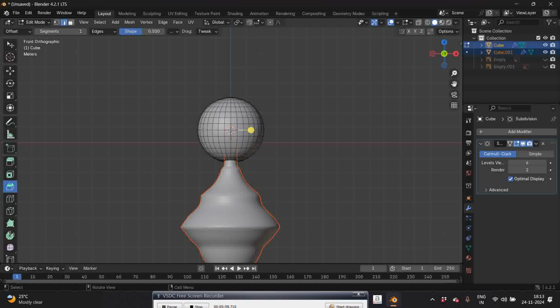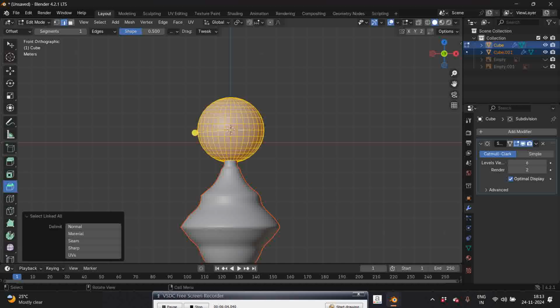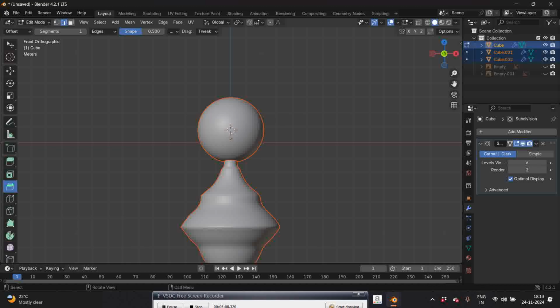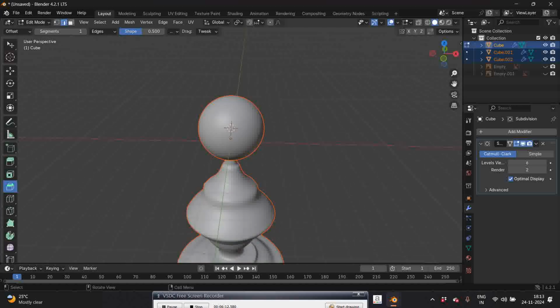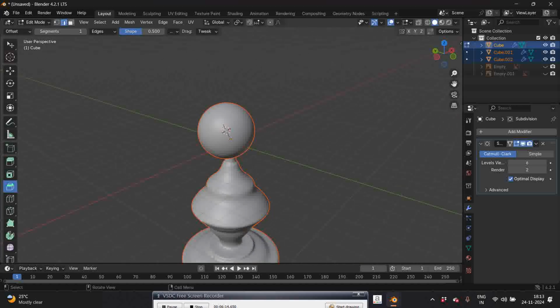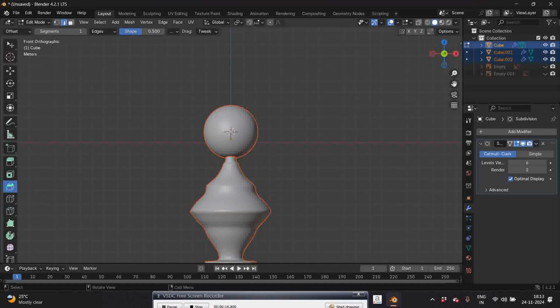So now it's this one also: select, Control L, select, then press P, and like that you can do the selection. That means this is a different object and this is a different object, and you can scale it, color it differently, whatever you want. Okay, now again you set yourself to a view mode.